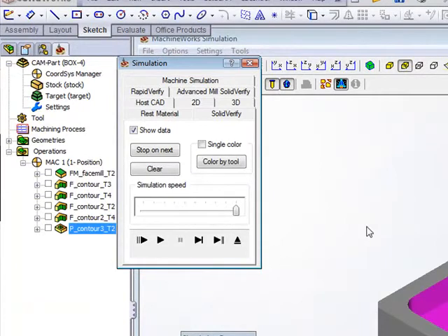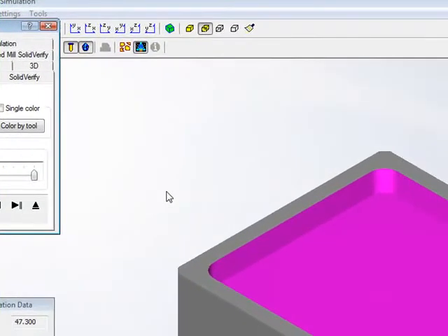itself. Now, what I'd like to do possibly is, instead of going directly in with the end mill into the material, another possibility would be if I wanted to drill beforehand. Let's say I'm doing some kind of hard material where I prefer not going in, even using a helical move, I'd rather drill first. So what we can do is as follows.